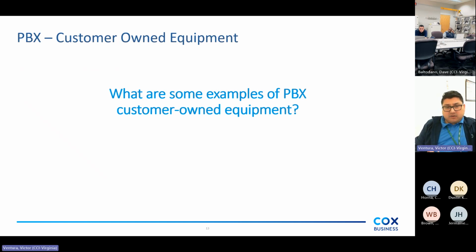One of the things I like to call out is that when the technician is connecting to a phone jack and they're using your toner, that could be your Fluke, or that could be your Greenlee toner, there are two LEDs on that tone generator that indicate if there's an active line on that phone jack. There'll be a green LED if you have an active line. There could be a red LED also if there's an active line.